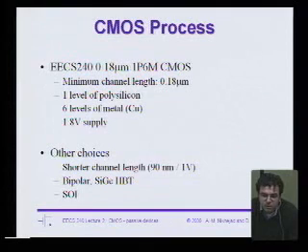So we've gotten to the point where analog performance and RF performance can't really keep up with the technology scaling. For some time, technology scaling benefited both analog and digital, but today, as we scale technology, it actually gets harder and harder for analog to keep up with performance, at least traditional analog. Hopefully you guys are going to go out and change that, right? You're going to come up with new architectures that enable using 65, 45, and still get good performance. But if you use traditional analog techniques, what people do in industry, then you're basically going to pay a big price in performance. So the idea of having one process for your digital and another process for your analog makes a lot of sense.